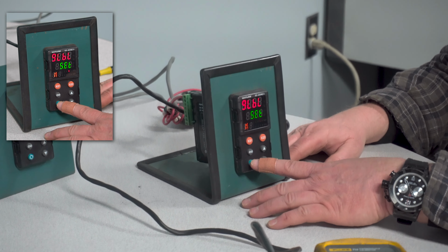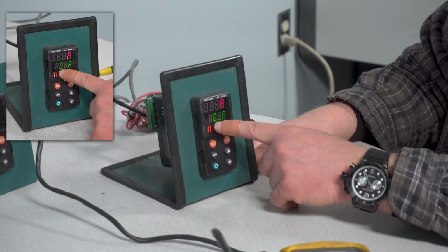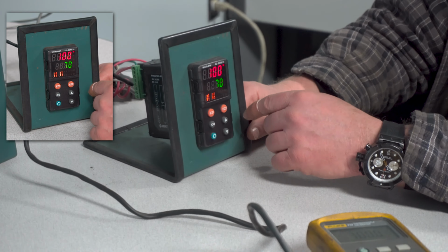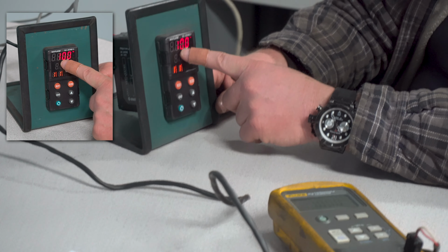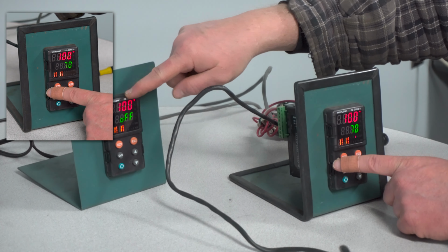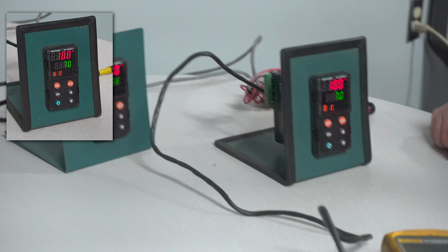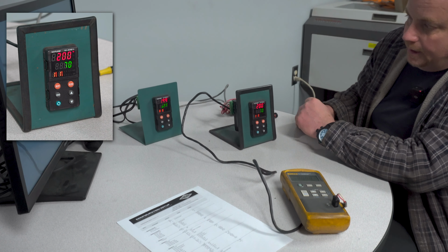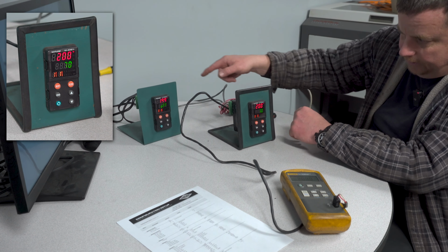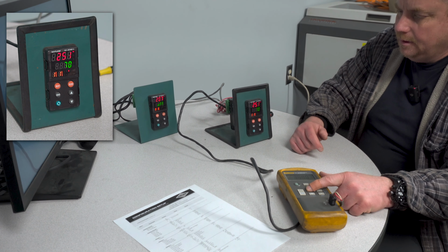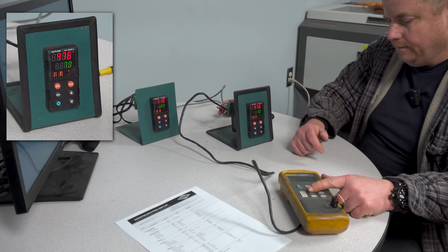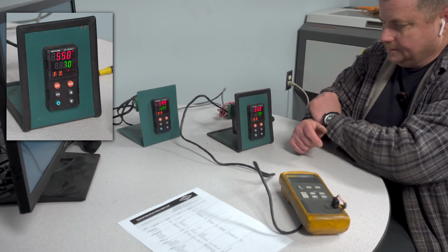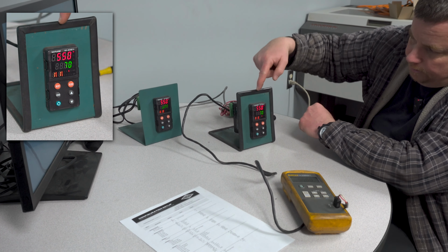We've shown you on the other ones, global, we would hit enter and we can change it from Celsius to Fahrenheit. I'm just going to back out. And you can see right now we're reading 100 degrees and we're retransmitting 100 degrees. So when I change this to 200, it's going to change that 4 to 20 milliamp signal to get us another reading on the other. So if I go up to 550, which is our max, you can see we read 550 on both.